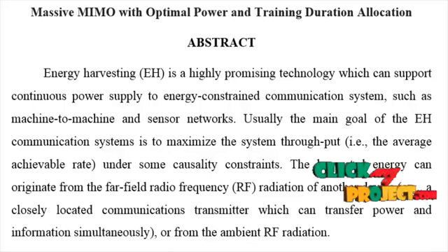Finally, for an interference channel with more than 2 transmitters, it is also possible to specifically design transmit signals so that the interferences are always constrained to confined subspaces at each receiver. This allows the receiver to efficiently reject the interference. This idea, known as interference alignment, has been shown to achieve significantly improved multiplexing gain for the MIMO interference network, where both the transmitters and the receivers are equipped with multiple antennas.